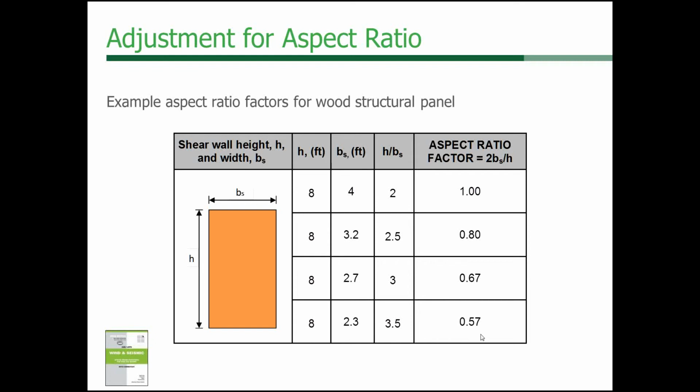So take this into consideration when you're laying out your shear walls: you're not going to get that much out of those really narrow shear walls. And I realize sometimes the architectural design really doesn't give you any options. You've got to use that wall no matter what because you don't have the luxury of those longer walls. But it's just something to consider.